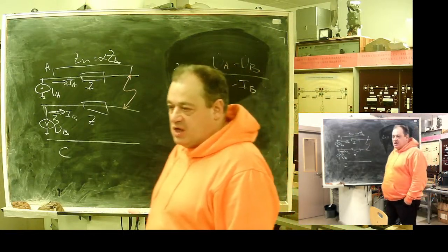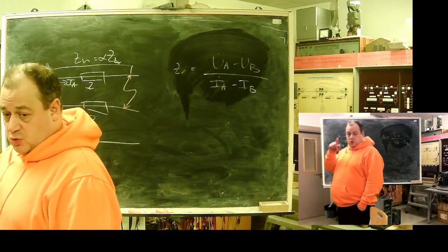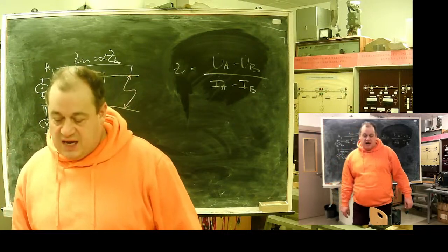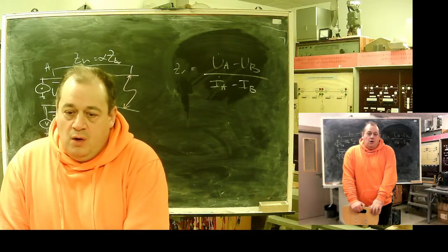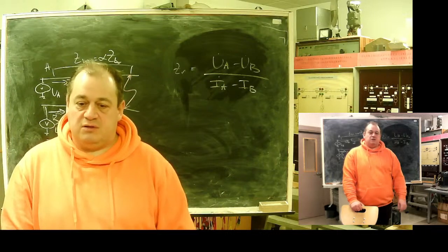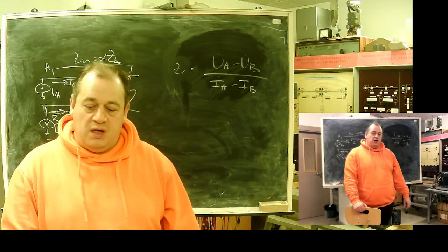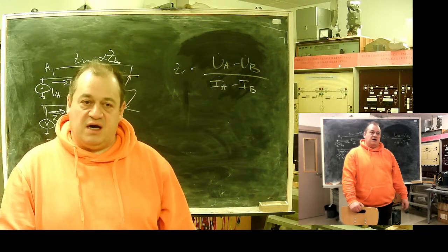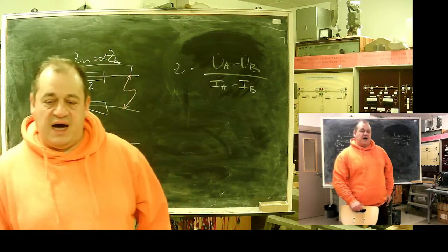This branch is a thing I should note: in distance protection there are two separate and independent branches. One branch, or set of processing flow, is for phase to phase, and another for phase to ground. They are separate.